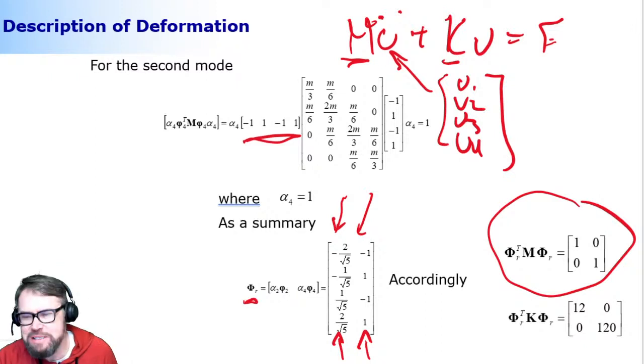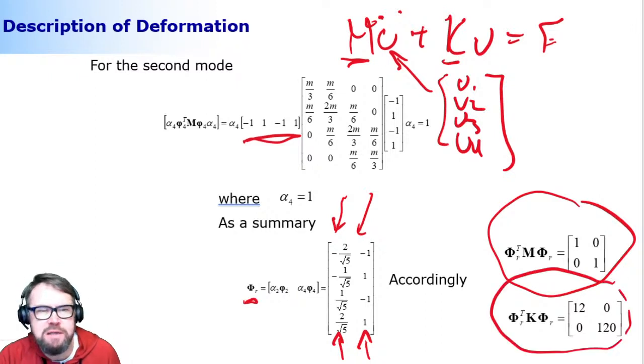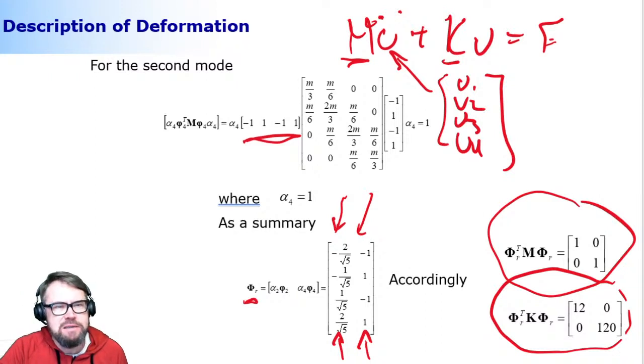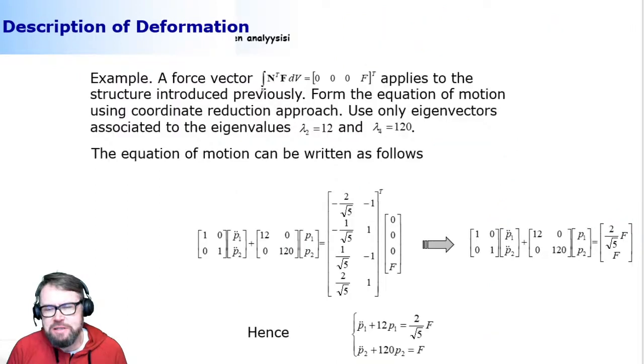Hopefully it's clear. So this is how my modal inertia looks. This is how my modal elastic or stiffness matrix looks. Now they are diagonal representations. And because they are diagonal representations, finally, my equation of motion looks like this. And look at this. This is super pleasant.